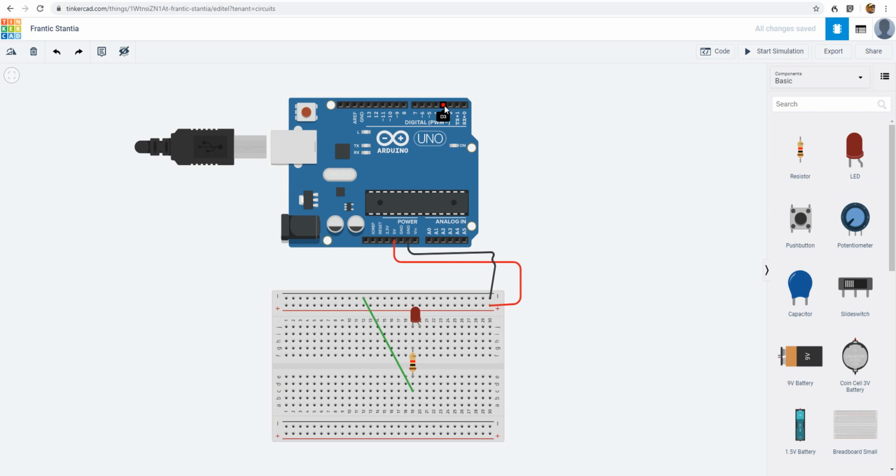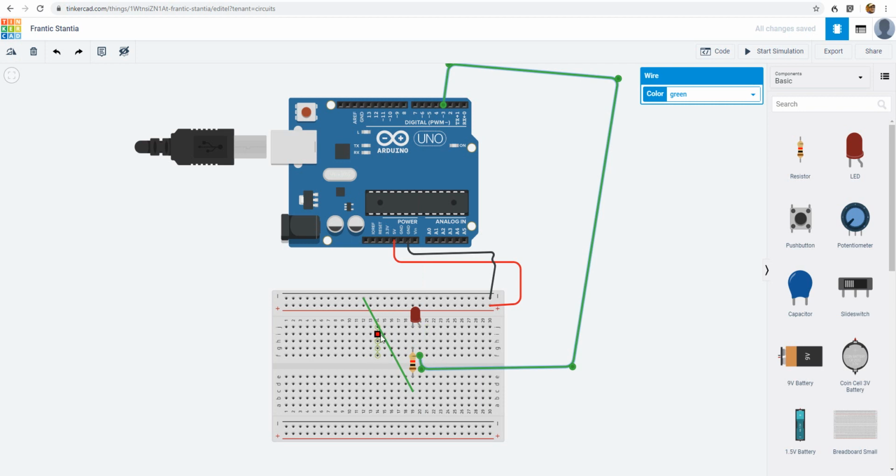So I want to create a program, and then that program will tell the LED light to blink. If you follow the tutorial, there is a code in the tutorial to do that. Then, connection wise, I'm going to connect port number 3, bring it all the way to the longer leg of the LED, which is in row 20. So I'm going to connect this one to row 20. Done. I forgot to change the color of this wire to black.